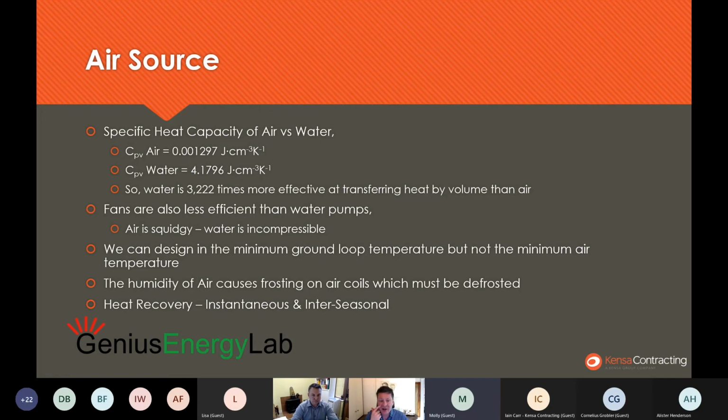So it's an effect that happens. It happens quite often in our winter because we're never cold enough for the air to dry up like we are in Scandinavia. And ironically, a heat pump running at 0 degrees in the UK, air source, would probably be less efficient than a heat pump running at -10 in Scandinavia because it's not getting that defrost cycle. So I can't really quantify it for you exactly at the moment.